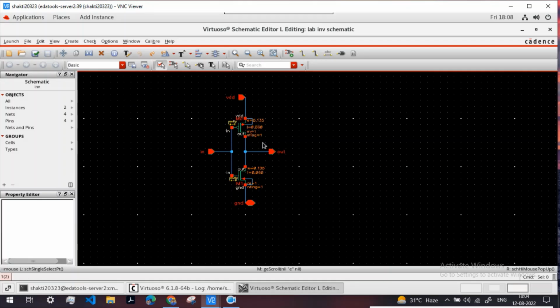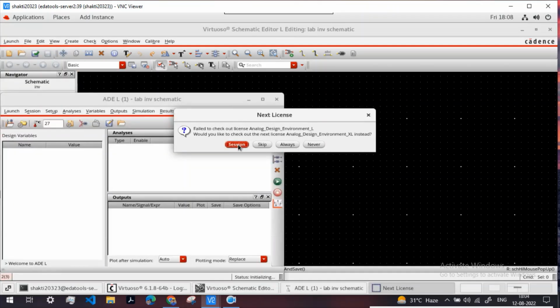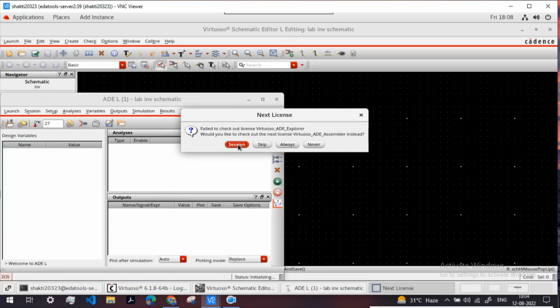Next, to perform the simulation on ADE L, you need to go to launch and then ADE L, and then you need to click on session. So keep on clicking session.